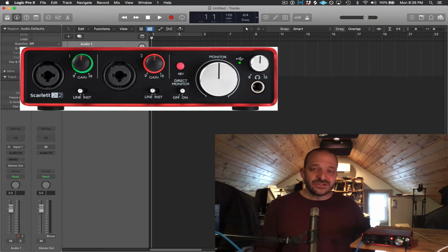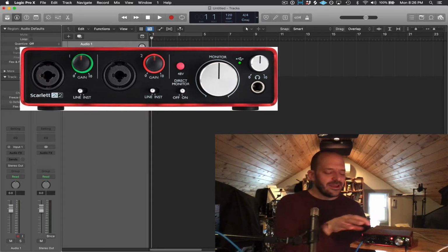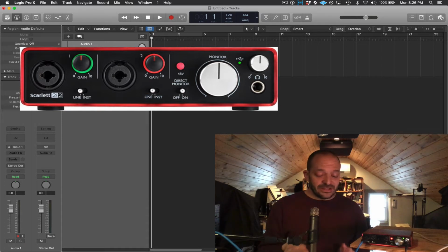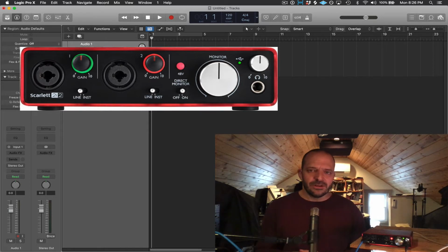It's always safe to start by turning off your computer first and then plugging in your audio interface's USB cable to the computer and then turning on your computer. I even like to have all my mic and instrument cable connections made to the interface before I turn anything on. But these days, most things are plug and play, so you shouldn't have a problem plugging the audio interface into your computer after the computer is already on.